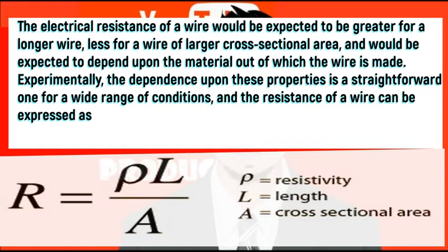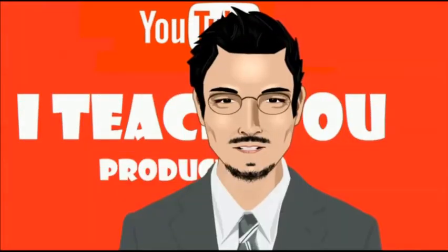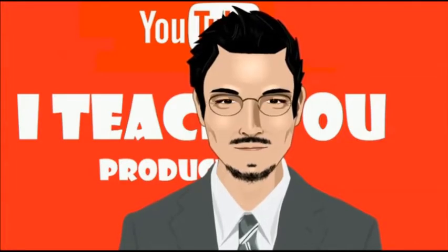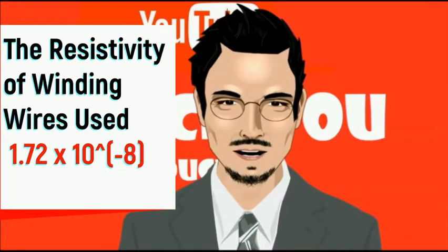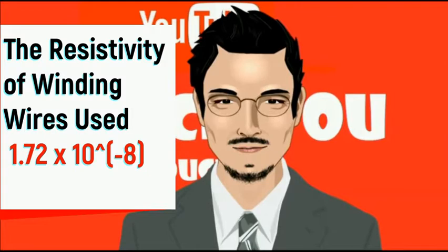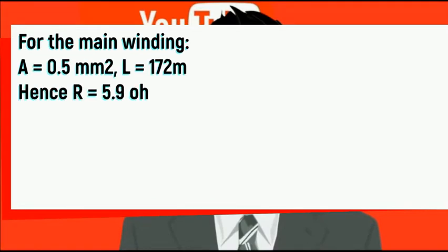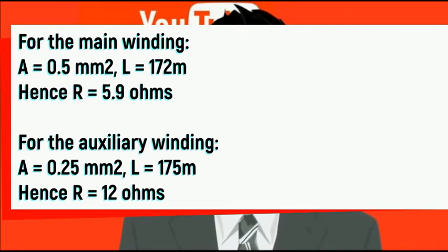Hence now we know the total lengths of each winding and the cross-sectional areas. The resistivity can be obtained from the manufacturer of winding wires, and for the wires I'm using here, the resistivity is given as 1.72 times 10 to the minus 8. Therefore, if we calculate the resistance of each winding, we end up with the following findings. For the main winding, A equals 0.5 square millimeters, L equals 172 m, hence R equals 5.9 ohms. For the auxiliary winding, A equals 0.25 square millimeters, L equals 175 m, hence R equals 12 ohms.